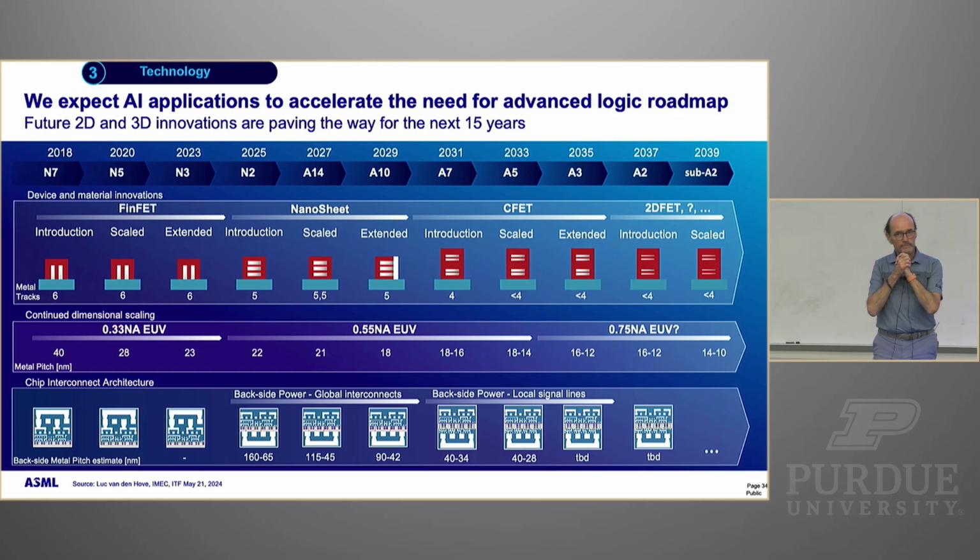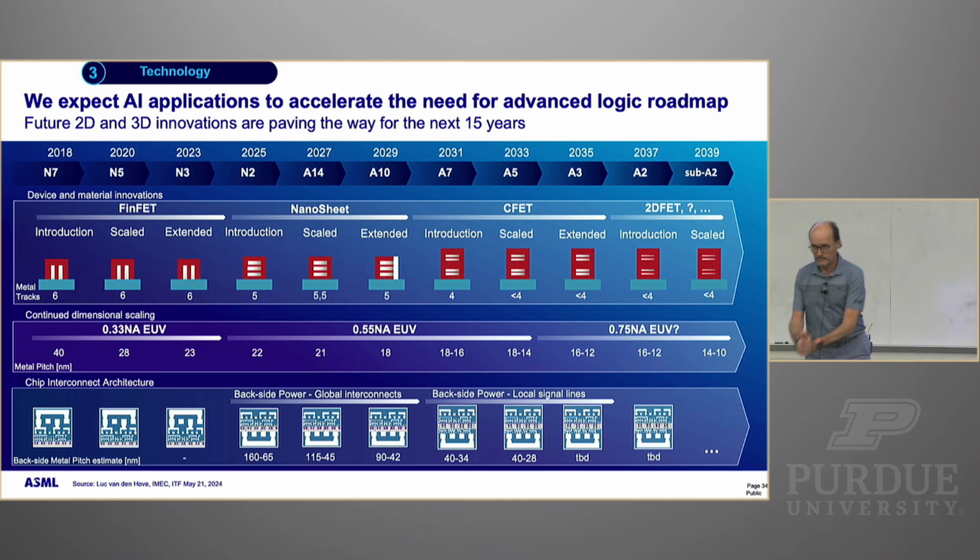Then we said, but if I've now taken the width of the transistor, which defines the amount of current, and folded that up, so that's now basically the height of the fin. From a semiconductor technology perspective, when I had planar MOSFETs, it was simple to make a wider transistor that had more current. I just changed the layout. But now I can't do that. So if I need more current, I need more fins. Now, but that's going to take up more space.